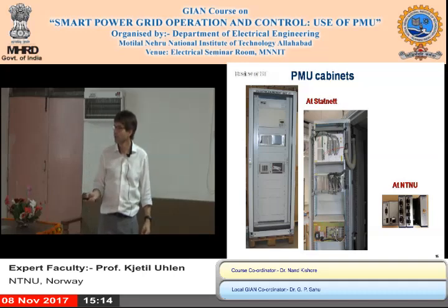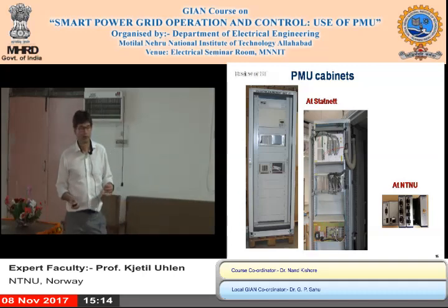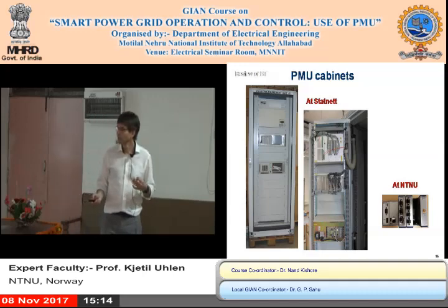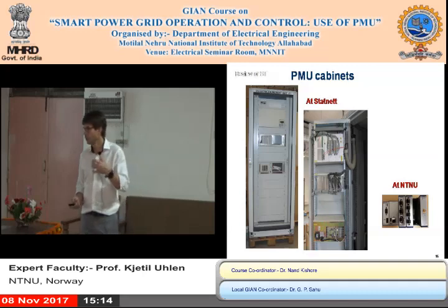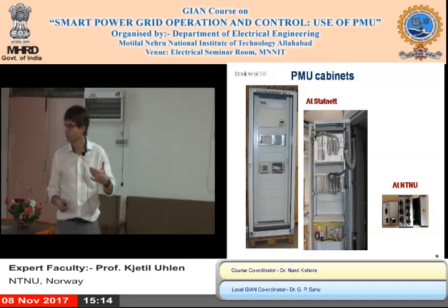What we have in our lab are PMUs that are implemented on the hardware of National Instruments. So this is basically what's called a compact RIO chassis, where we have partly implemented the software ourselves, and there's also open software available. National Instruments has their own software you can also use in LabVIEW.